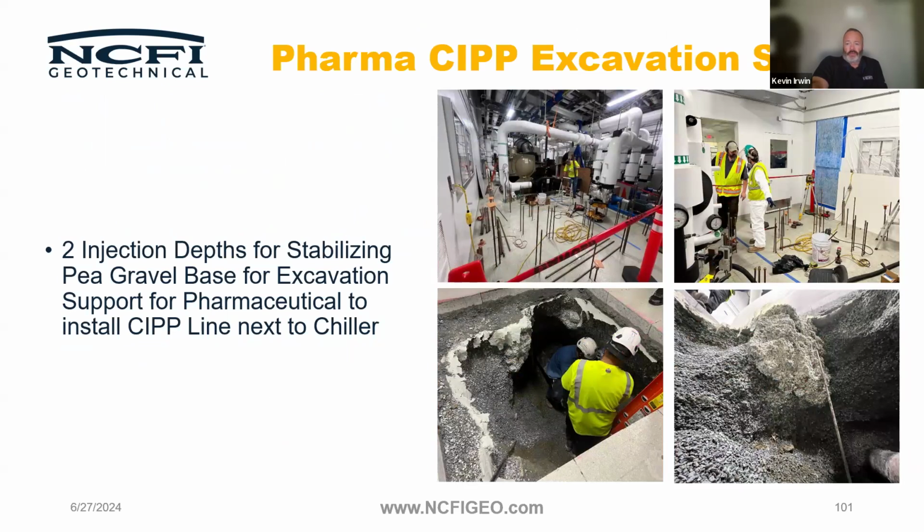This was a CIPP excavation support. Had a lot of gravel pouring in. This looks a lot like how we do it in Arkansas. We have a great fill product here in Arkansas, but it's made of flaky byproduct from shale processing, and it's great for a fill under a slab, but it's really horrible to try and dig through. It tends to collapse in on itself.